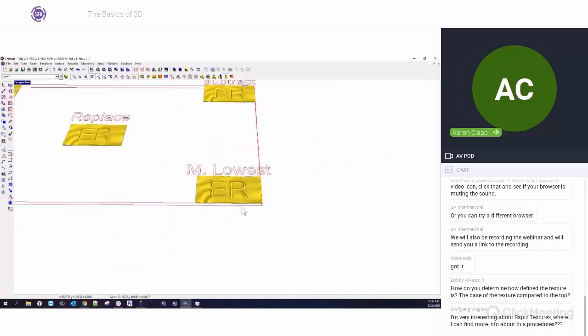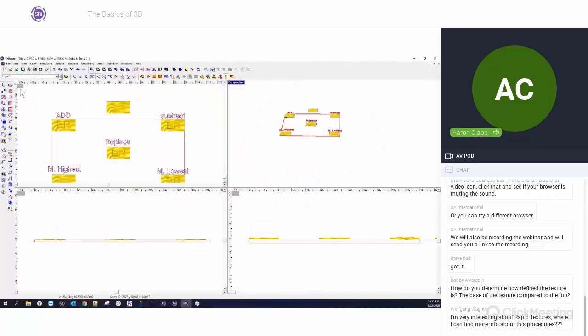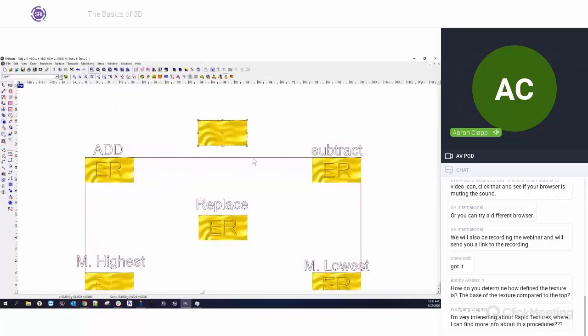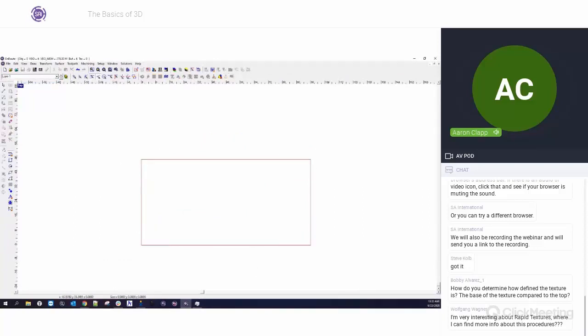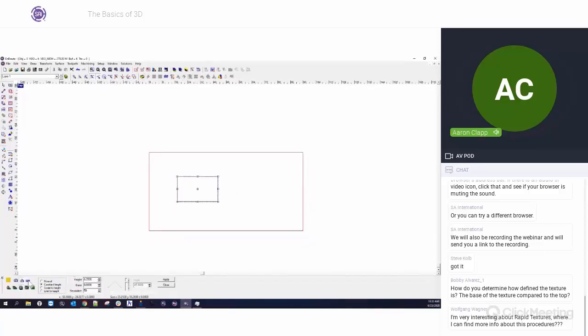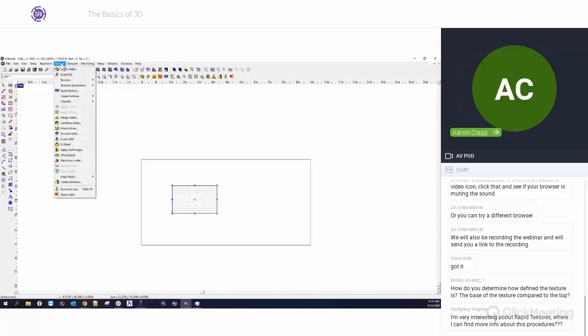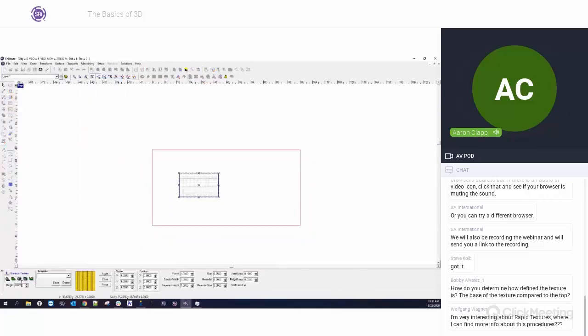I want to do one quick example, and this might help visualize why maybe we want to do one over the other. Let's go to a new layer, or let's just delete these, and let's go here. I'm going to create a base relief of flat, no thickness, normal, apply. Okay, and then I'm going to apply a bamboo texture. And we're going to say this is going to be 0.5 inches tall. And that's fine with me. We're just going to do an add, apply.